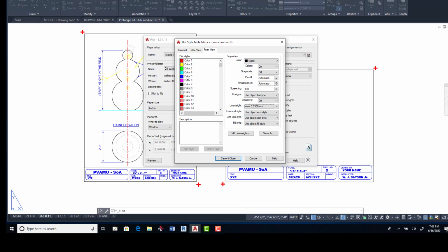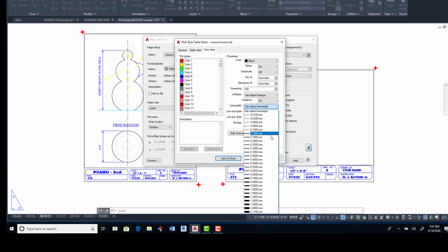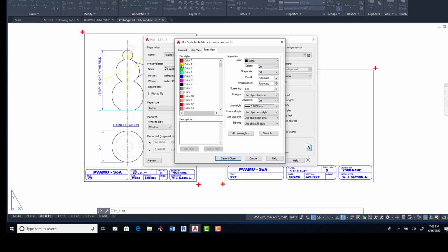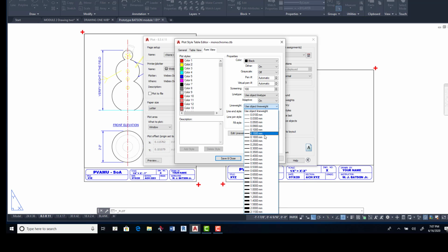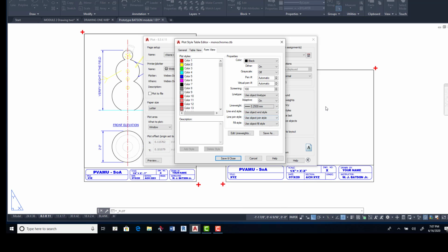Now blue is the text, right? So that line weight is 0.2. And yellow is the object, that's 0.25. So let's go back over that. Color number 1 is 0.01. Color yellow is 0.25. Color blue, text, is a medium line weight of 0.2. Color number 7 is 0.45.